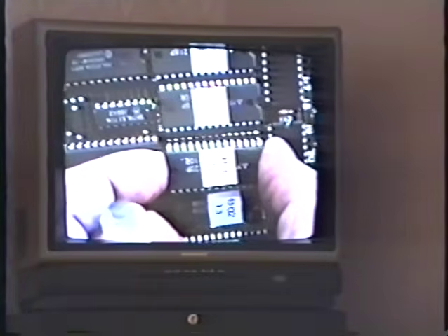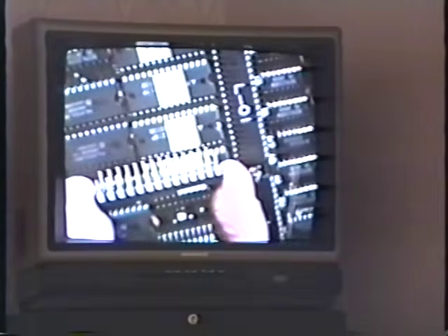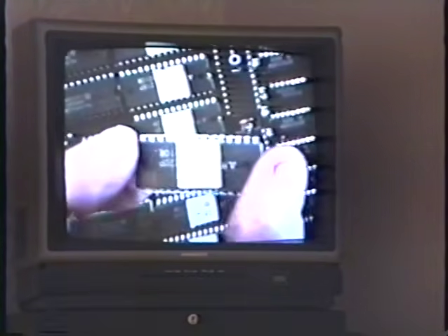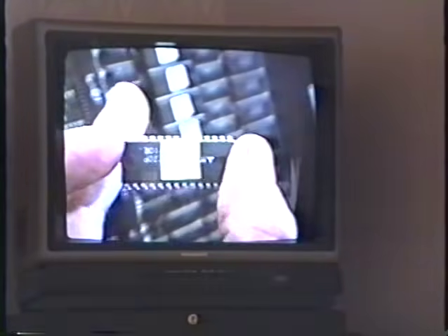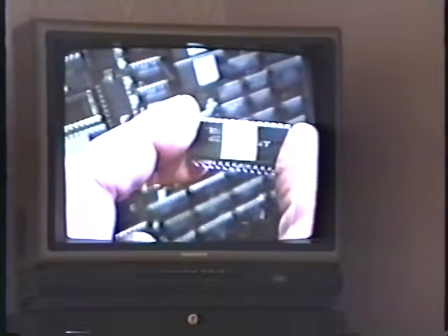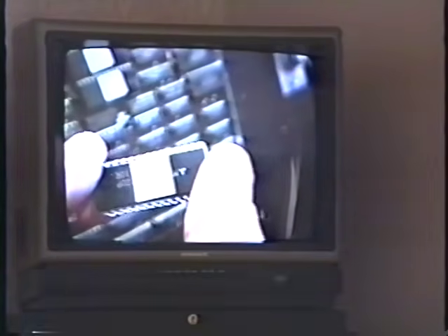Never, under any circumstances, try to pull one of these chips out with your hand without a screwdriver, because you'll get one end loose, it'll go up like this, you'll bend the little pins, and maybe if you're lucky you can bend them back once. But if you break a pin off, these integrated circuits are custom integrated circuits. They're called ROMs, read-only memory. They contain the program information. They contain the rules of the game, how the computer makes the game appear on the screen, the images, all kinds of stuff. And I don't know which ROM contains what. It depends on the game. Probably the one that I pulled out contains some kind of image information, because that's the only thing that's screwed up, huh?